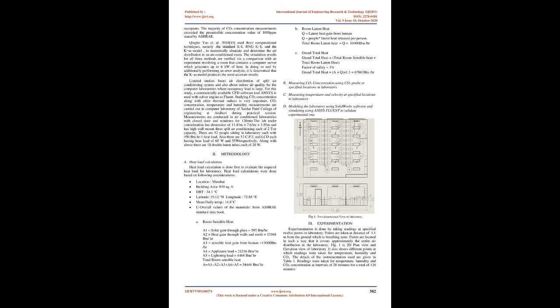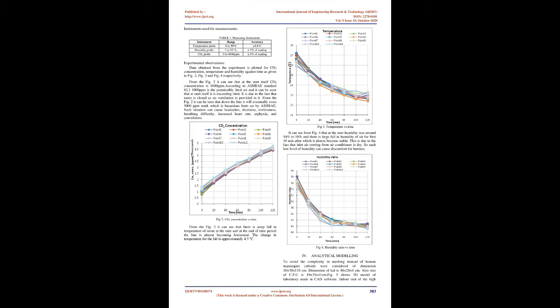M. Hassan et al., 2017, evaluated the indoor CO2 levels in 10 mechanically ventilated laboratories and identified necessary improvements. High CO2 concentration in laboratories 1 and 10 indicates a minimum laboratory ventilation rate as specified in the codes. CO2 levels should be reduced to produce laboratory environments that are conducive to learning. The other laboratories had CO2 concentrations lower than 1000 ppm.